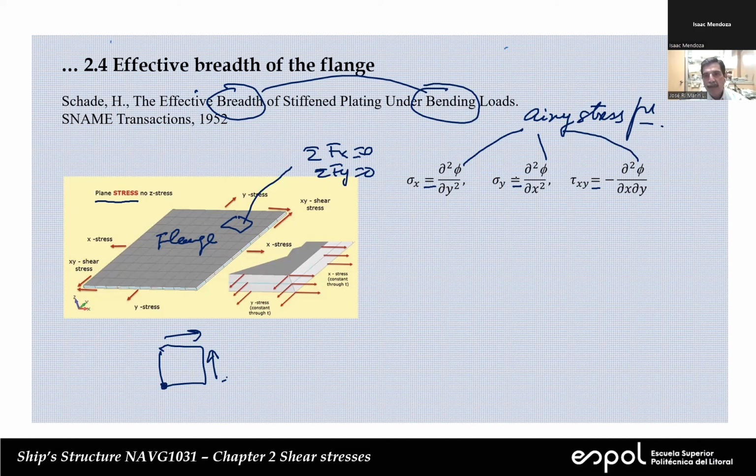Now, if we do this and plug it into here, you will see that these equations of equilibrium are completely satisfied. So if we define phi in this way, the equilibrium equations are completely satisfied. Usually, up to now, we try to solve the equilibrium equation, and by solving it we find the solution of our problems. Deflection, and differentiate that, and we get moments and all of this.